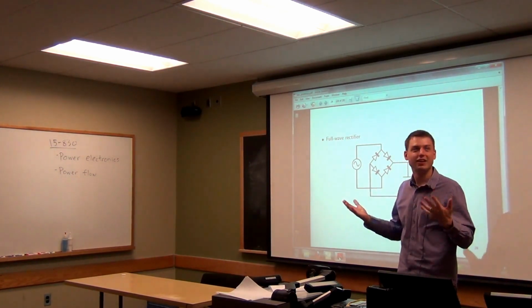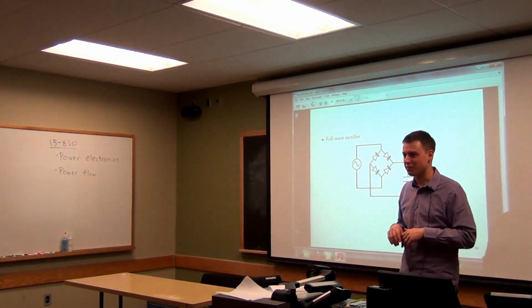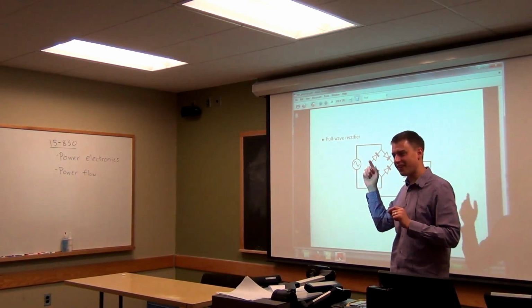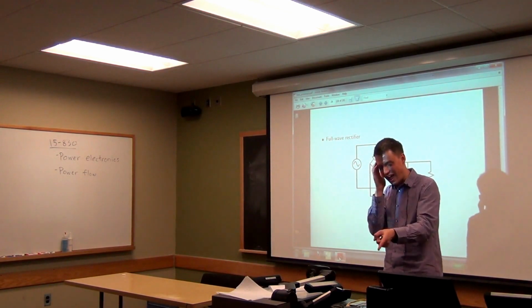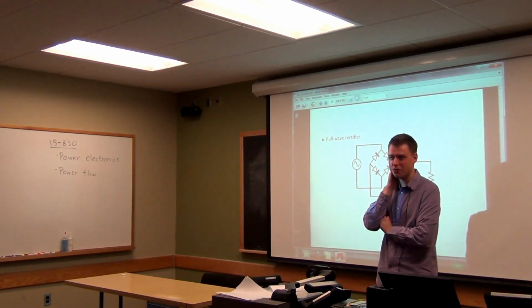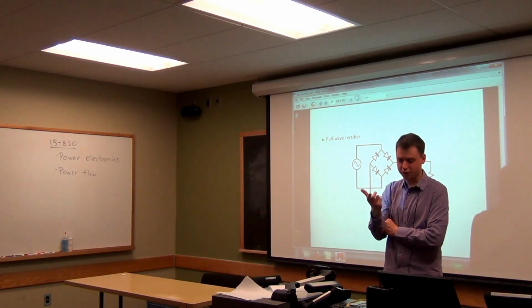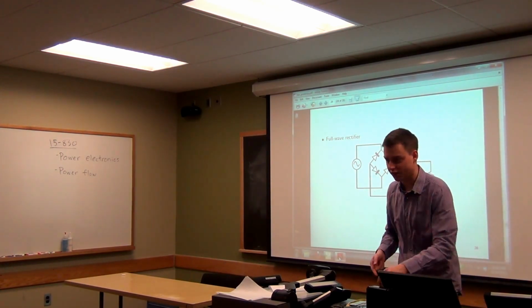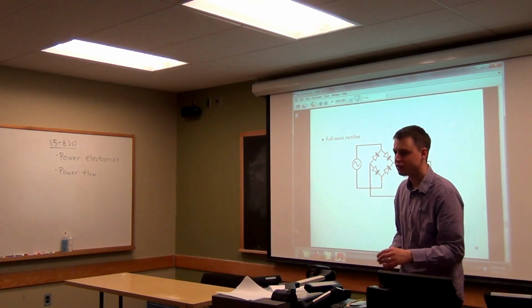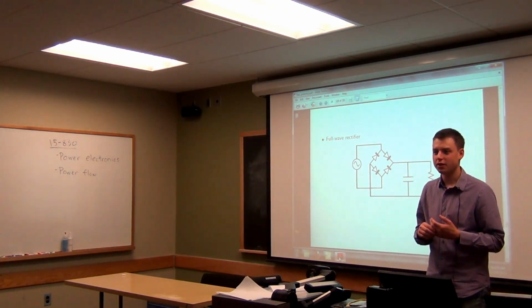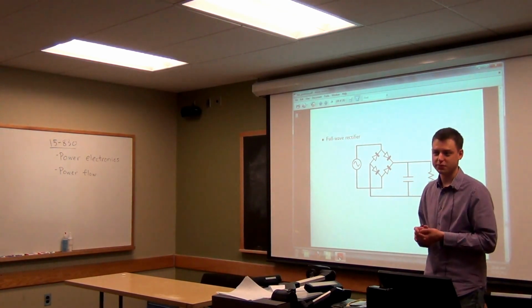I mean, maybe you could design a circuit that would work that way, but it wouldn't matter, because using 60 hertz AC power or AC current to power something like that would be pretty tough. It's much easier just to use DC there because the clock cycle of this is in the gigahertz range, right? So we're talking about very, very fast changes. You really need DC power for that. You need a DC source for something like that.